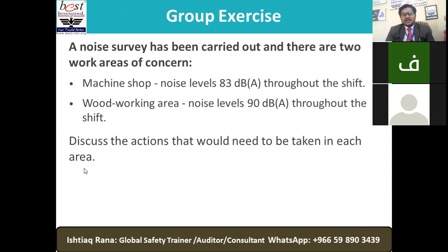Will you go back and see whether the preventive maintenance plan is being followed and the regular maintenance is done? Any noise coming from the friction of that machine, maybe lubrication problems? You will find out the source of that sound, exactly from which part or area of the machine, which machine is noisier.